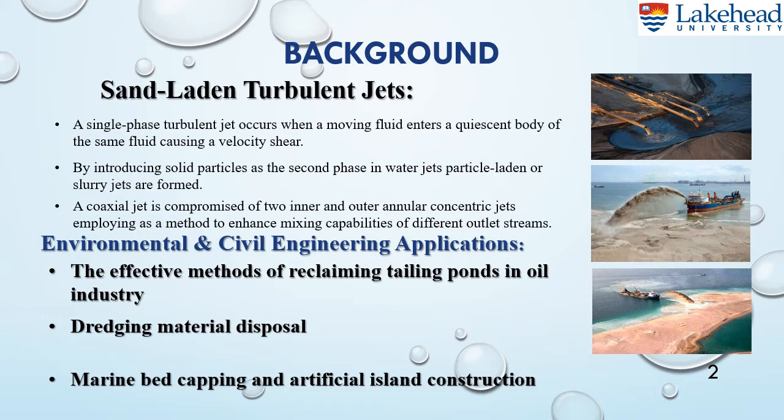By introducing solid particles as a second phase in a water jet, other water jets, particle-laden or slurry jets can be formed. A coaxial jet is comprised of two inner and outer annular concentric jets, employed as a method to enhance the mixing capability of different outlet streams.